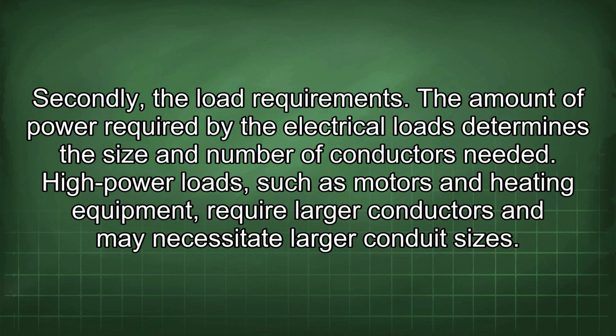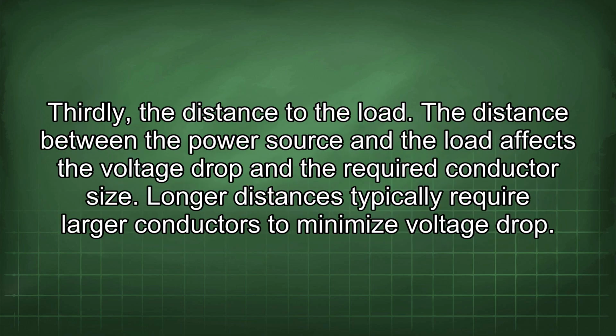Secondly, the load requirements. The amount of power required by the electrical loads determines the size and number of conductors needed. High power loads, such as motors and heating equipment, require larger conductors and may necessitate larger conduit sizes. Thirdly, the distance to the load. The distance between the power source and the load affects the voltage drop and the required conductor size. Longer distances typically require larger conductors to minimize voltage drop.